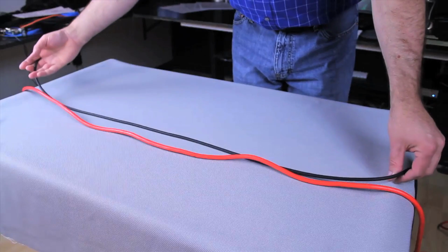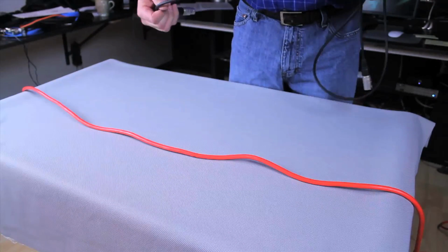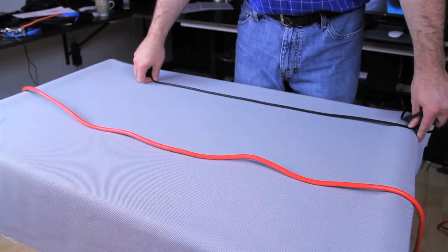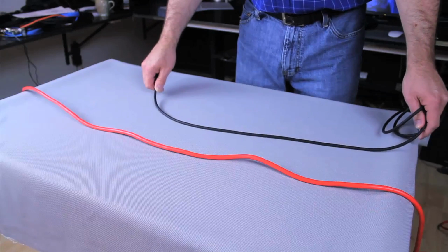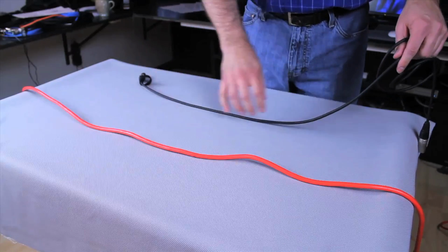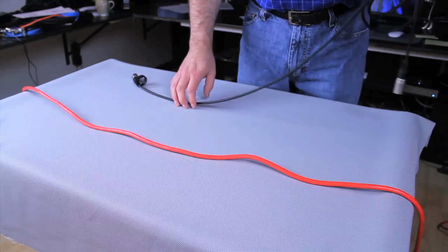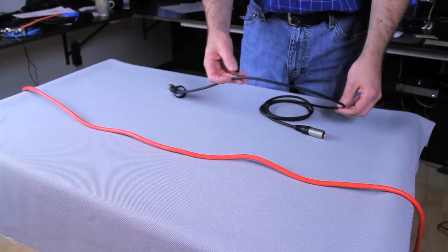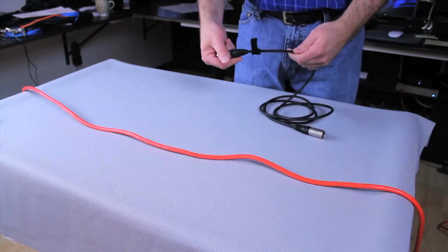Don't ever do this. And the same thing goes for video cables. If you see a video cable laying there, it's a lot more powerful than an audio cable. It's carrying higher signal. Try to observe the same rule. You are going to get RF in there. And with your audio cables too, if you run a whole bunch of them in a bundle, you run that same risk. Very low risk, but you still run that risk if one of the audio cables doesn't have good shielding. If you follow your location rules and you have good shielding, you should avoid a lot of those problems.